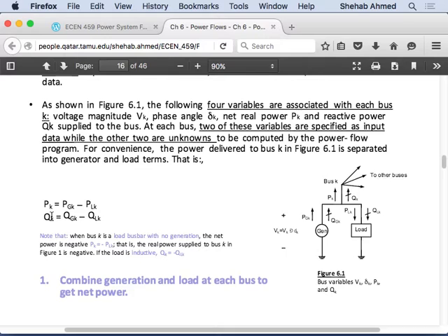And that's what we were talking about from a utility perspective: a generating power station would typically have a certain power limit it continuously provides, right? That's why I said if a bus has a generator at it, I typically know my real power capability and my voltage, because this power plant, I cannot just shut it down, right?